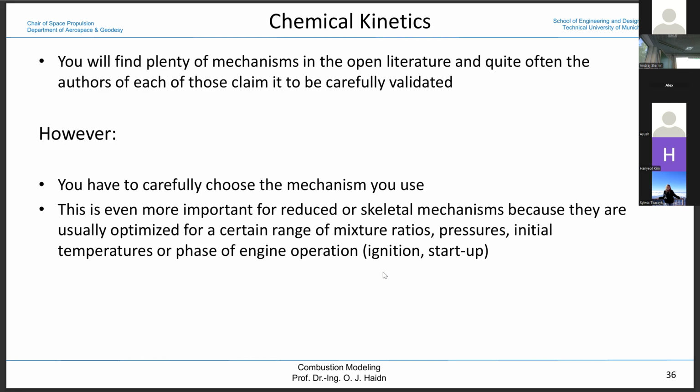It's even good for boundary layers, but because of the recombination reaction in the boundary layer, due to the large delta T and the fuel rich conditions, we are changing the composition. So we change the species concentration, we generate heat, species with different heat capacity as well as thermal conductivity. So the boundary condition will be entirely different when it comes to heat load to the combustion chamber wall.